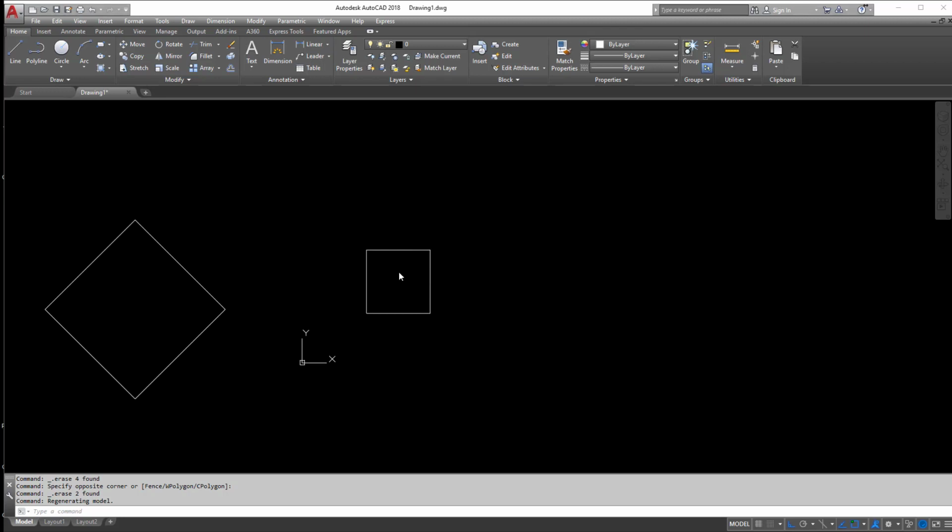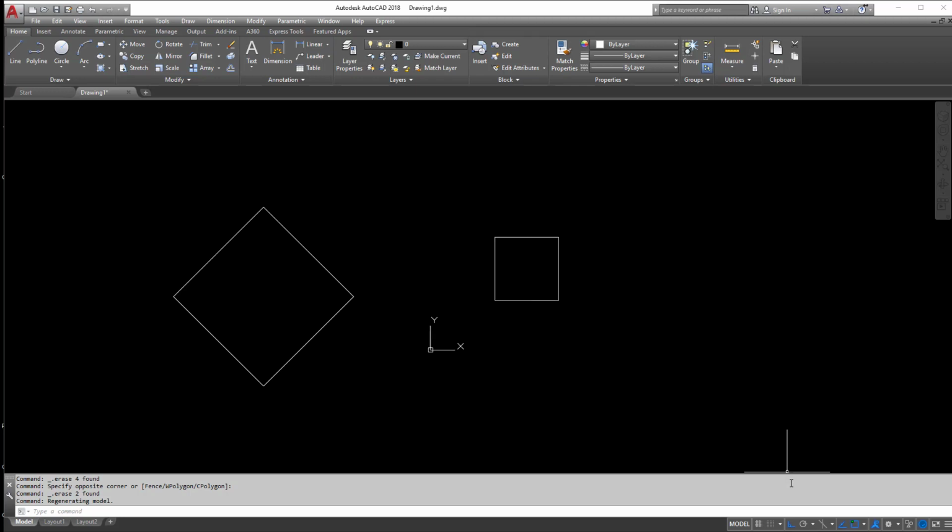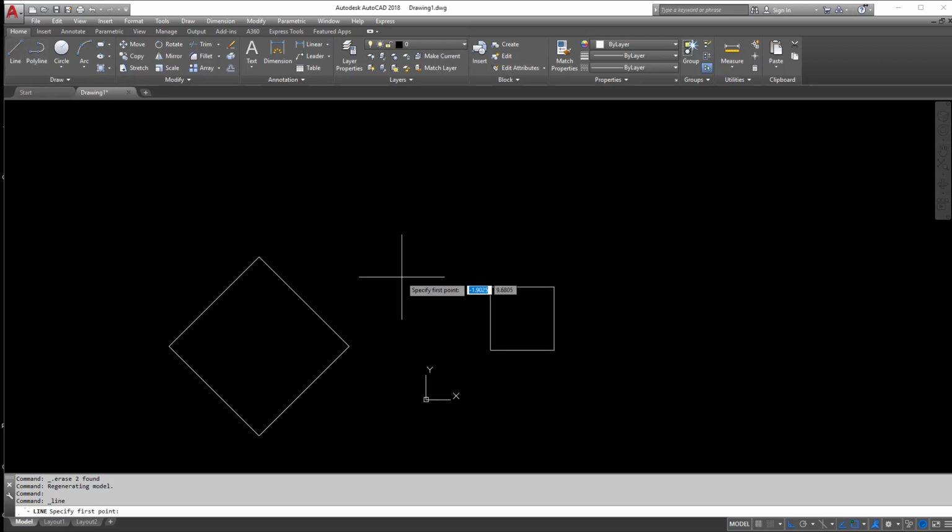All right, so getting back to here again. So again, there's a few different ways to draw lines. Those are the most popular ones, I feel. There was an old school method that you could do. If I turn off dynamic input, so there's this little customization button here, and it'll be cut off a little bit on the screen here. But you'll notice one of them in here is called dynamic input, and I'm going to turn it on. So pay attention over here. You'll see it pop on. There it is right there.